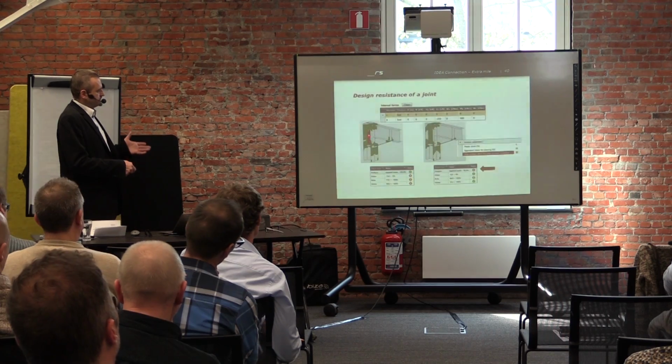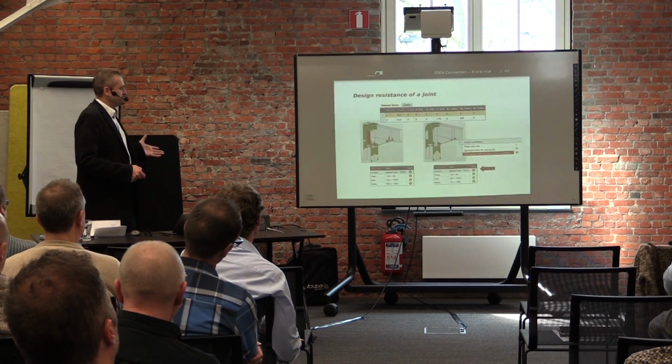One of them is how to analyze the resistance, or design resistance, or limit resistance of the joint. When you input your loads, they are in fact internal forces which are calculated in your 3D program, internal forces in the frame, and you get the results like that. There is a problem, or it is green and there is not a problem.